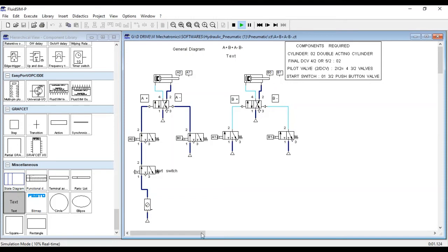So here the pressure switch is there. Here pressure is coming, and you can see what I have just told, that both pilot switches have pressure, because A0 is also on and B0, both are in retracted position, so both valves are on at the same time. Because of this there is no change in the position of the valve and there is no motion of the piston. So this is a major fault in such kind of circuit.